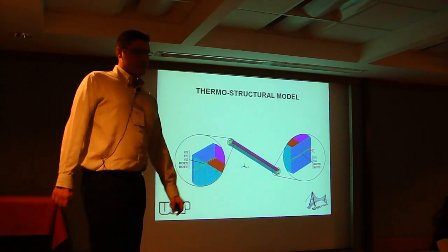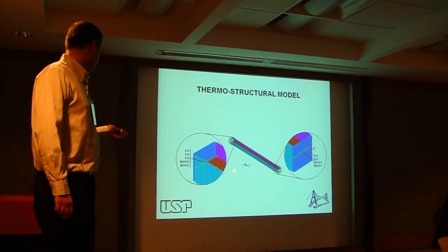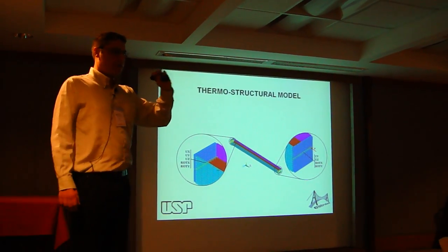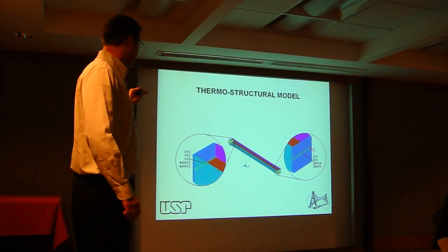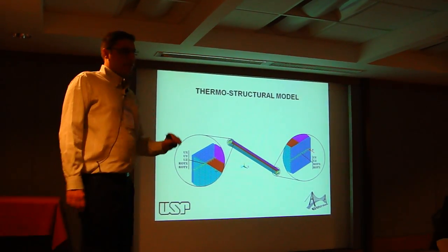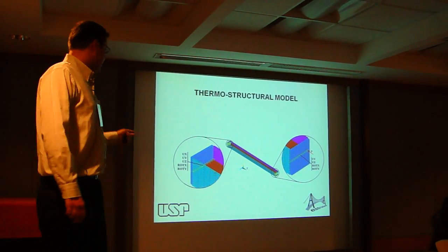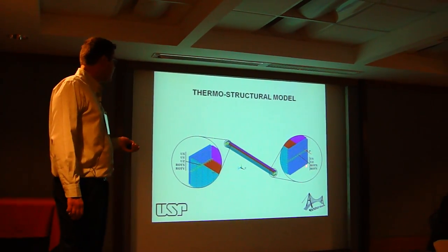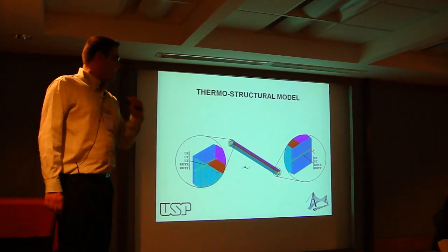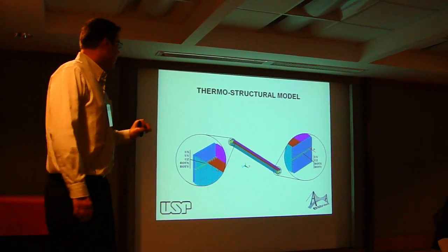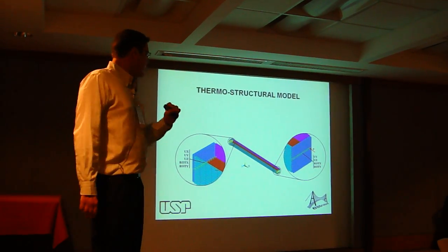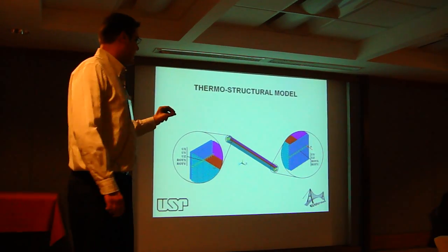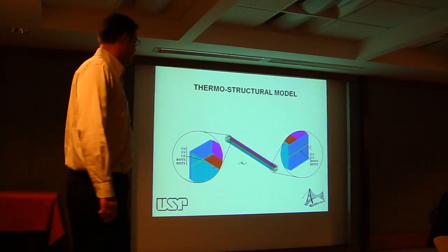On the bottom end plate, a line of nodes above the web, all the degrees of freedom are restricted except the rotation about the weak axis. And on the top end plate, a line of nodes above the web, all the degrees of freedom are restricted except the rotation about the weak axis and the longitudinal displacement.